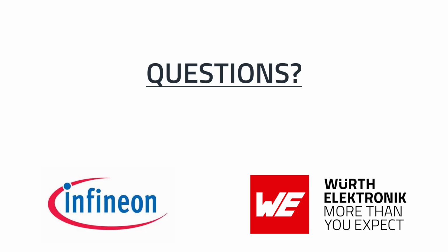Thank you very much. Our next question: why is leakage inductance so critical in power gate transformers? Well, it again depends on which parameter you're prioritizing, but leakage inductance acts like a speed limiter in your gate drive path. The higher the leakage, the slower the gate charge and discharge will be, which means you are slowing the switching. So you are also going to have more switching losses.